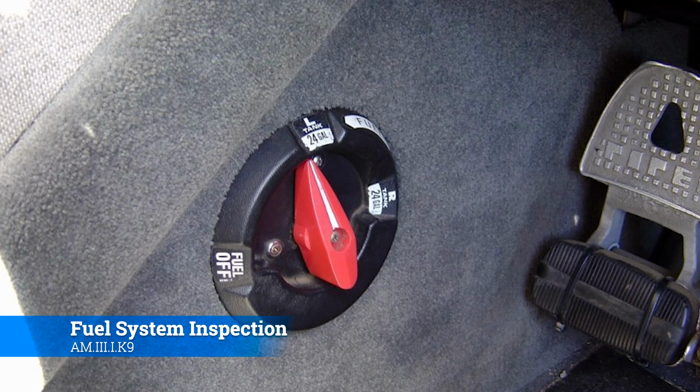The Cherokee selector valve right there is just going to spin by your hand, but you could end up in a situation where you have electric fuel valves, and you need to make sure that you actuate them. You hear them go. You can check them by whatever means the maintenance manual requires you to do it, be it with a multimeter or just simply by visual.